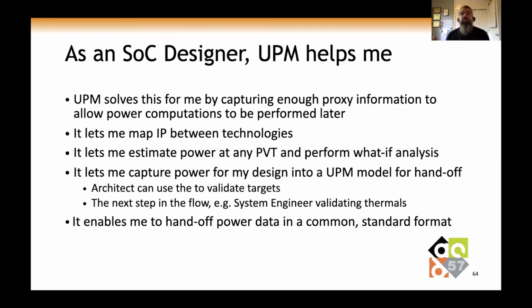Most importantly, it allows me to estimate power at any PVT point. This allows me to do what-if analysis, to do trade-offs, and to make sure I'm meeting my power targets. It also allows me to capture my power analysis data into file format and hand that off.